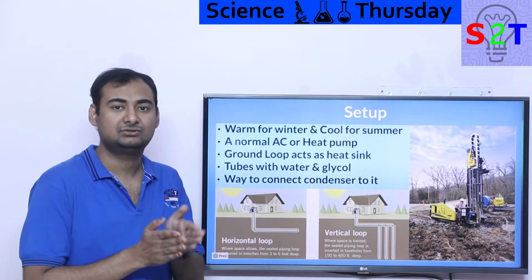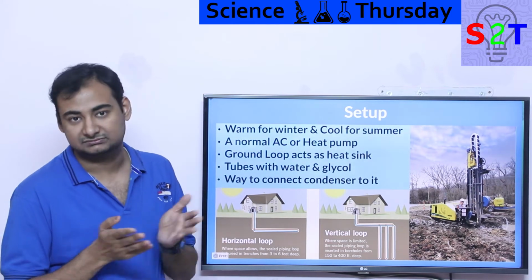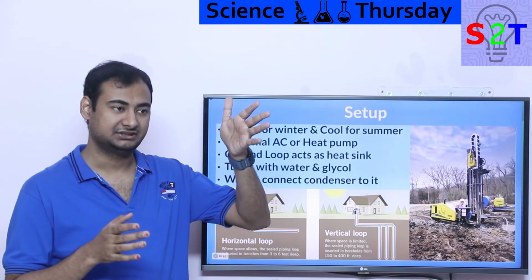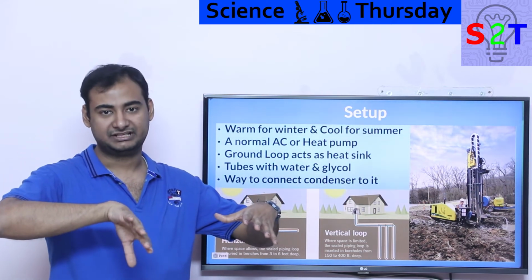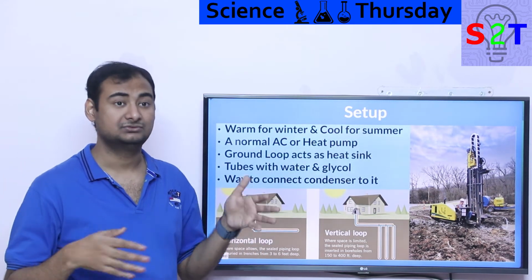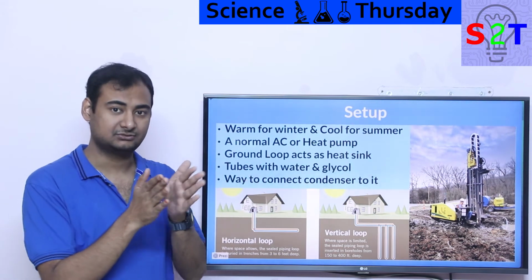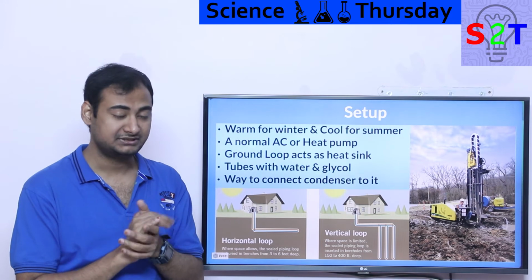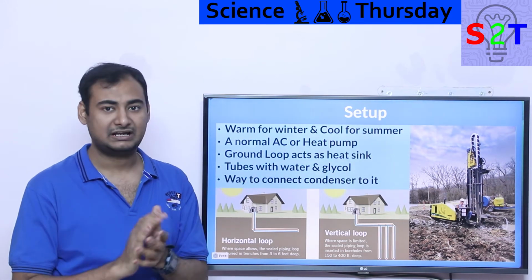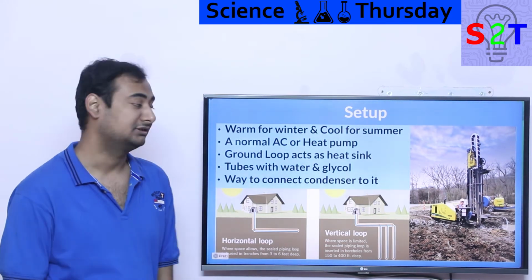And you have to figure out a way to connect the condenser. Now, some companies basically have the condenser unit in an oil tub, and there is another heat exchanger. That's much easier to connect compared to some systems which have liquid directly going through the refrigerant line. Now that heat exchanger is very expensive. Many companies do that, but it is expensive to do. So you can have different systems depending on your cost and money and all that jazz.